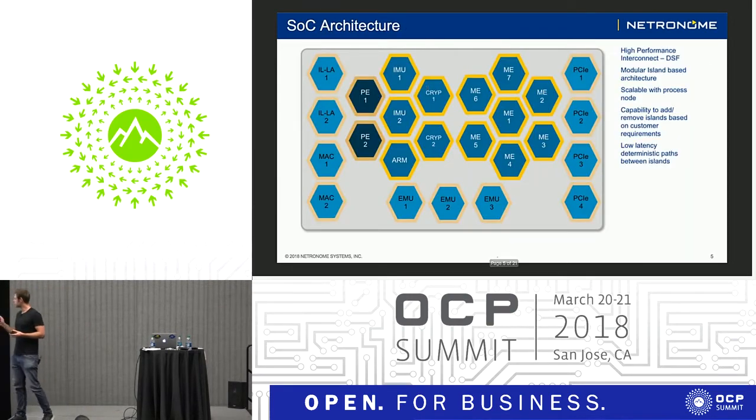One of the other things I should mention before I jump off this slide is that the reason this is all possible is because there's an extremely high-performance interconnect, basically a mesh, which sits underneath this whole thing. That bus is what allows us to pass information very, very quickly between different cores, which allows us to use this many-core model. It's not really even a multi-core model, it's a many-core model, because you've got a lot of interactions happening and about 500 packets potentially being processed at the same time. So it's kind of like a cross between an old-school CPU and a GPU.